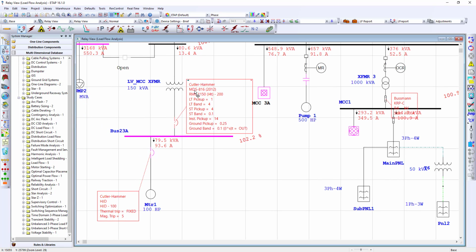I could see here that for my main Caterpillar MDS main breaker, the size is 200 amps. For my motor load breaker, I have a thermal magnetic breaker that is 100 amps. So since I'm going to be adding 3 more motors, I'm going to have to switch my main. I'm going to have to set new protected device settings most likely. And also, one of the things I need to do is change the main low voltage transformer from 150 kVA most likely to about 500 kVA. So let's go ahead and begin with the expansion.